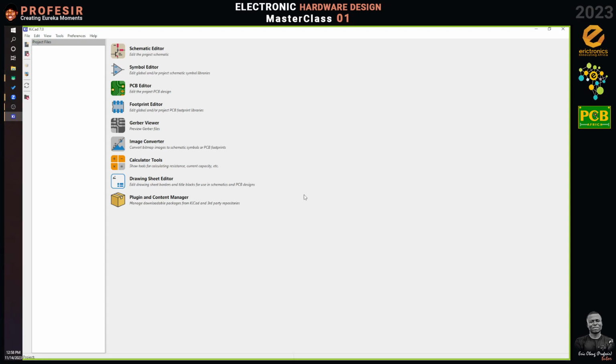When you launch KiCad, this is the first interface you will receive. This is where everything happens. You can call it the project manager. Is that okay? Basically you would see three primary interfaces. The first one, which is your starting point, is what you are seeing here, where you manage your entire project. From here you can see that we have other integrated tools. So we have the schematic editor, which I said is ES schema.